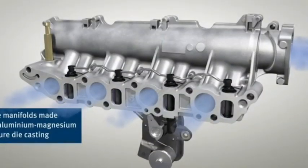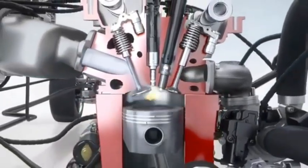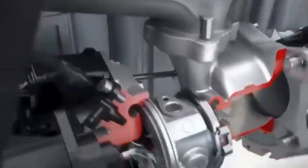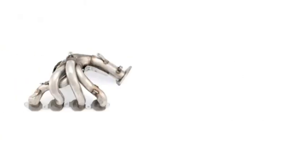On the other side, the exhaust manifold is also mounted on the cylinder head, and it's responsible for collecting exhaust gases from each cylinder after combustion and directing them into the exhaust pipe. While the intake manifold is often made from plastic or aluminum for thermal efficiency, the exhaust manifold is typically made from cast iron to withstand high temperatures.